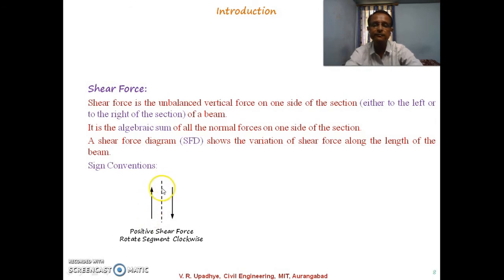And if we are considering the right part of the section, then the downward forces on the right part of the section will be considered as positive shear force. So these kind of forces which are rotating that segment clockwise are termed as a positive shear force.